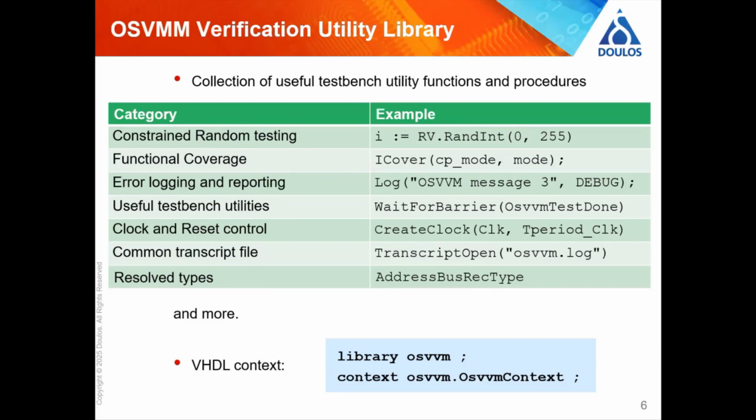We've got some test bench utilities for doing things like working out when we finish the test. So UVM has the objection mechanism for doing that. VHDL didn't have a really good native way of doing it, although we can kind of simulate it. Creating clocks and resets, which is something you could do quite easily in VHDL, but it's a bit tedious. And if I want a clock, do I really have to write the same code to generate the clock that I've done 10,000 times already?